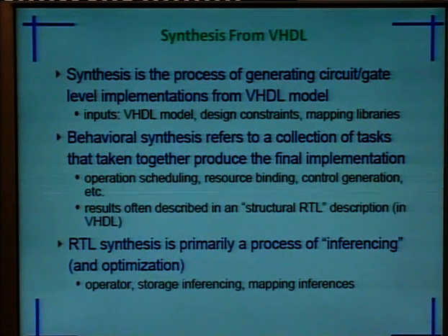Synthesis is the process of generating the circuit's gate-level implementation from VHDL code. This process will be useful for students who would like to work on minor or major projects based on VHDL. Once our code is ready, we have to verify it and implement it on the hardware with the synthesis process. Synthesis is basically of two types: one is behavioral synthesis and the other is RTL synthesis.